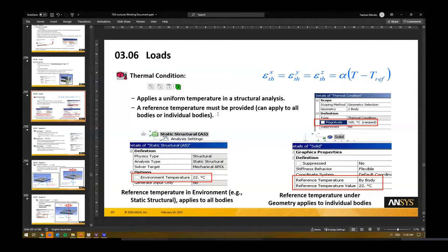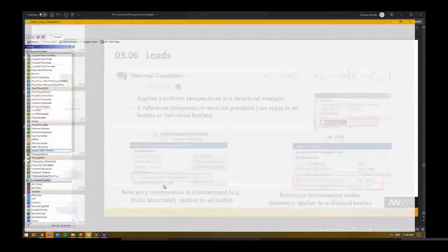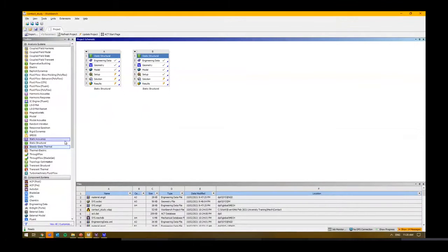So depending on your boundary conditions, you might want to think about what analysis systems you need, right? And if we've got more than one analysis system, so if it's a thermal analysis system, the other question you need to ask yourself is, how tightly coupled is the physics? Can I run the thermal analysis and then look at my results? Or will the thermal analysis deform the subject so much that we need to account for the structural results as well? In that particular case, we've got what's called a coupled field element, where we can solve both problems together, right?